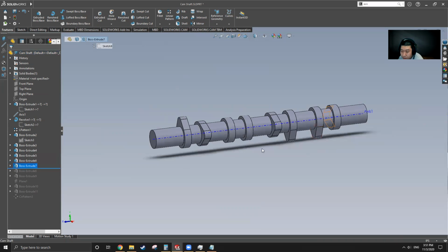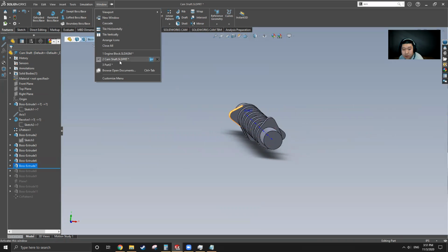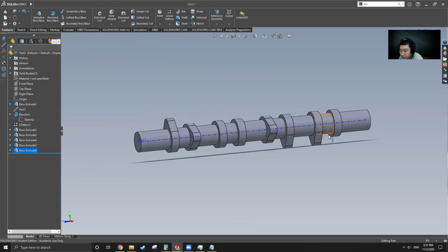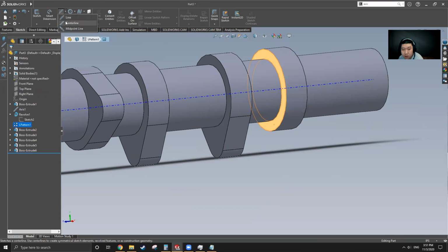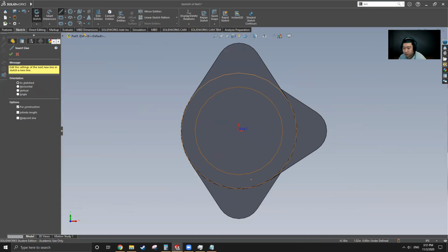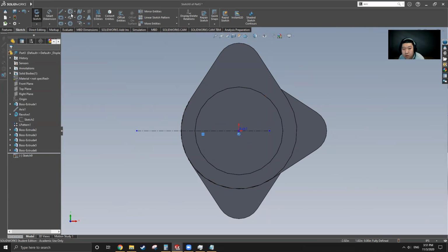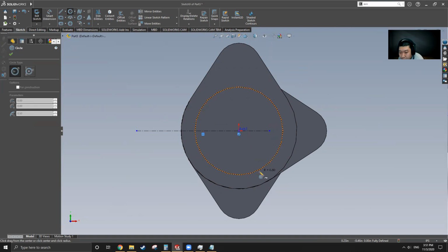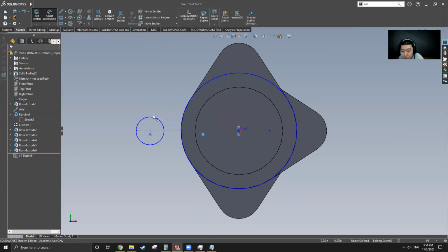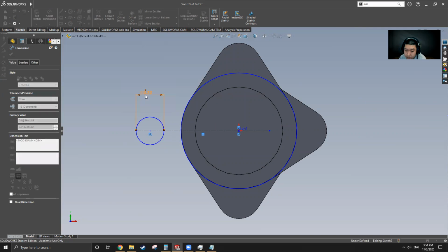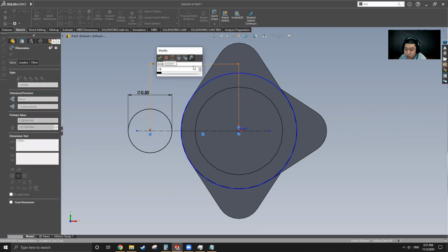Okay, for this one. So this is gonna be a brand new one because this goes left. Let's do it. So this surface, let's sketch, start with the center line, and get a normal to. So big circle first, and small circle. The small circle is to be 0.5. Center to center is 3/4.